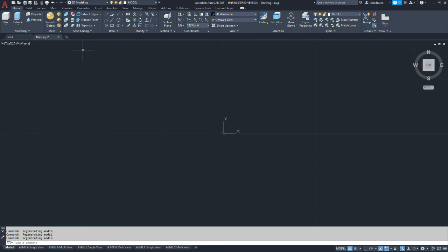So we're going to face it so that we're looking normal to the boss feature, and that way all our other views are more supplementary, and we're defining as many dimensions as possible off that main view. It reduces the reliance on hidden lines.